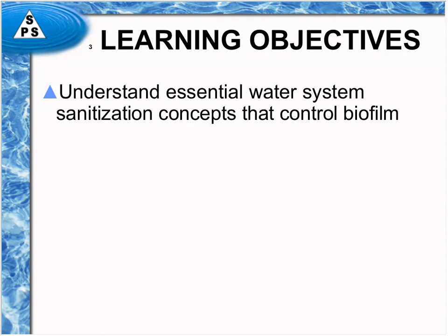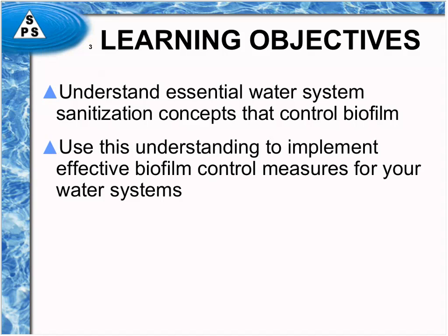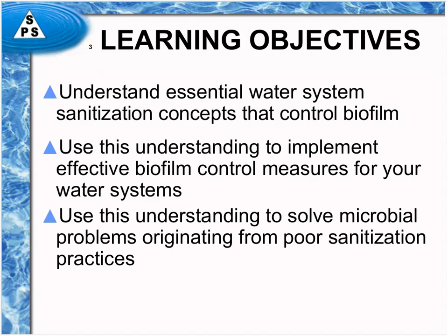Okay, the objectives of today's webinar are that you would be able to understand essential water system sanitization concepts. These concepts are designed toward controlling biofilm, which is how organisms grow in a water system. And with this understanding, it should allow you to implement some effective biofilm control measures for your water systems, and also allow you to solve some microbiological problems that may originate if you indeed had poor sanitization practices.